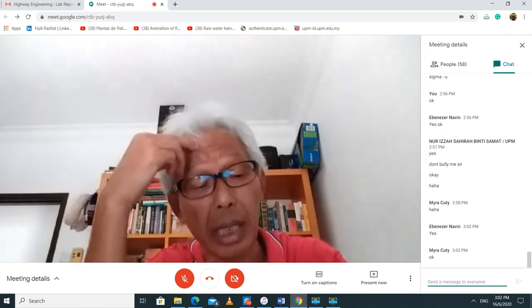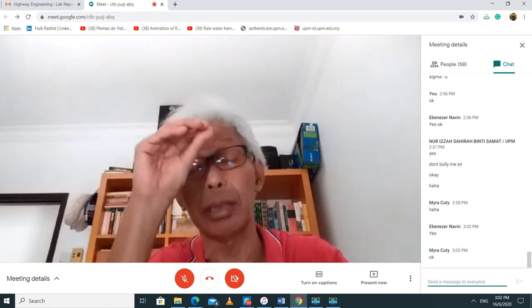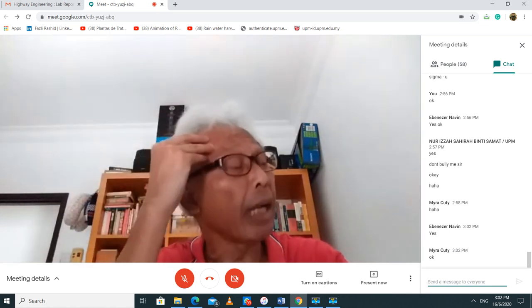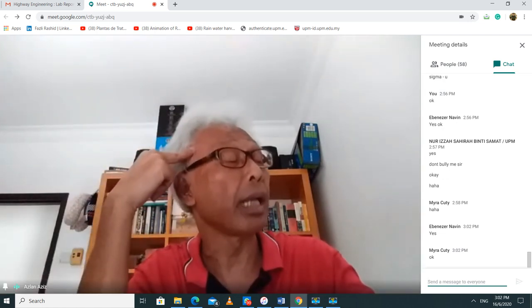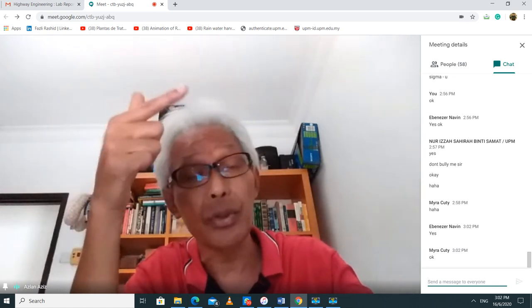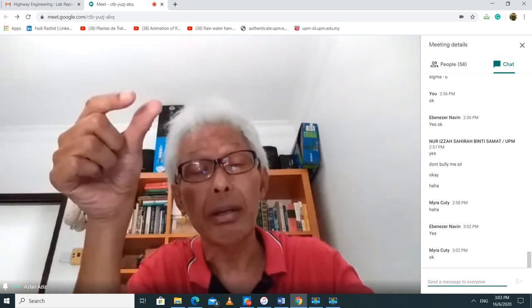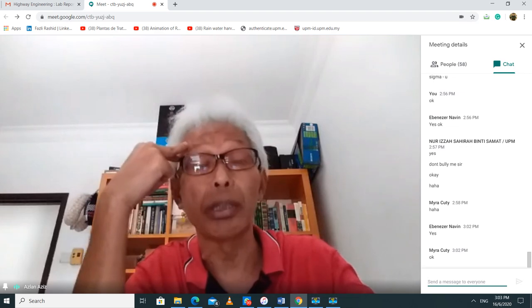I said to you that a Mohr circle is just a representation of the state of stress for an element. Okay, so I still have my Mohr circle there. But not only that, I have my total stress Mohr circle. I also have my effective stress Mohr circle. And they are just differentiated by the difference in pore water pressure.